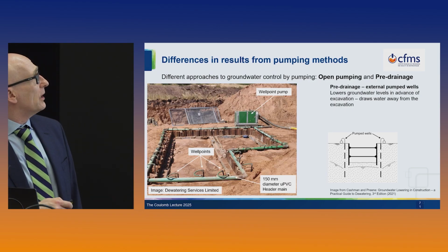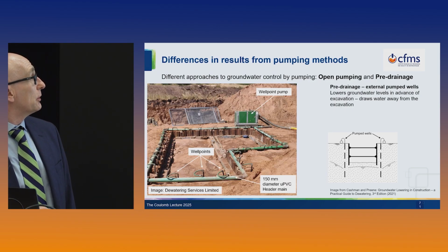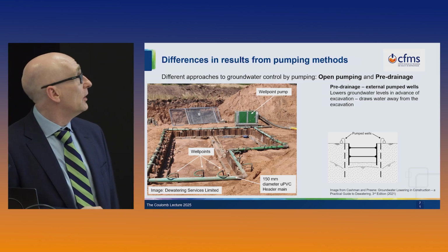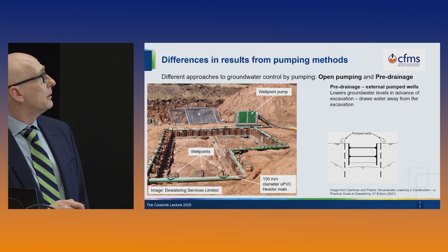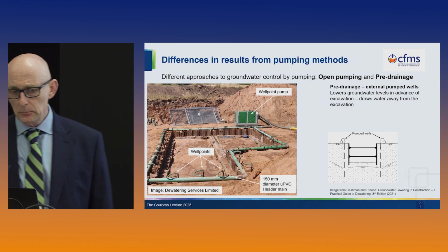Here's a small excavation inside steel sheet piles. It's only been dug down to 1 metre. It's going to be dug down after the photograph. But see here we have pumped well points around the outside, pumped by a pump there.